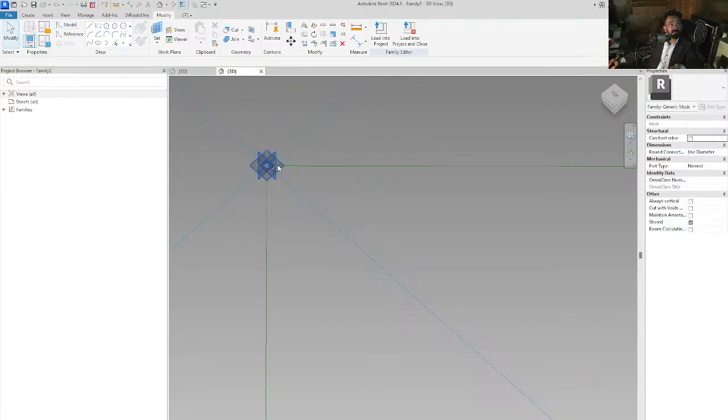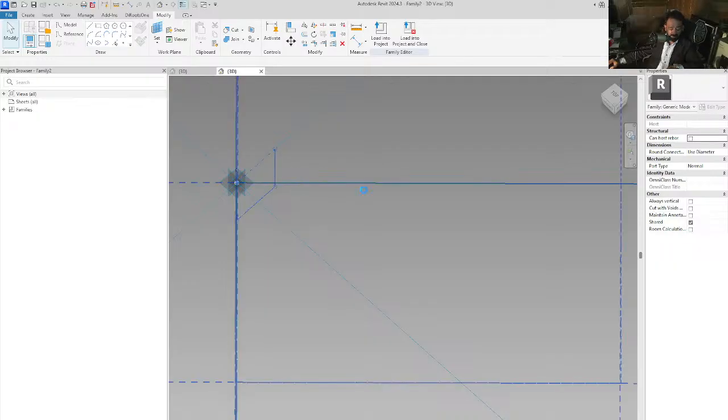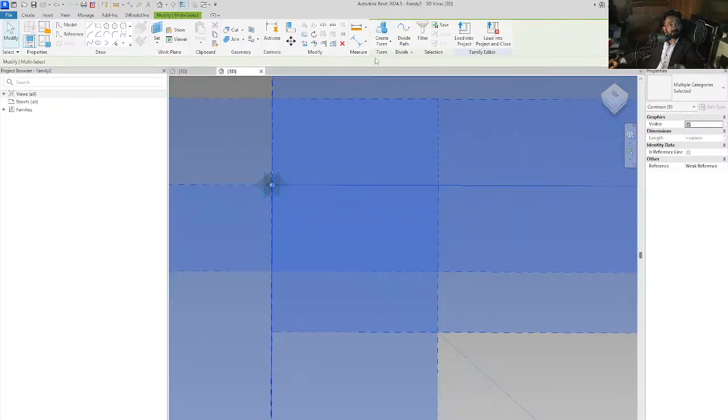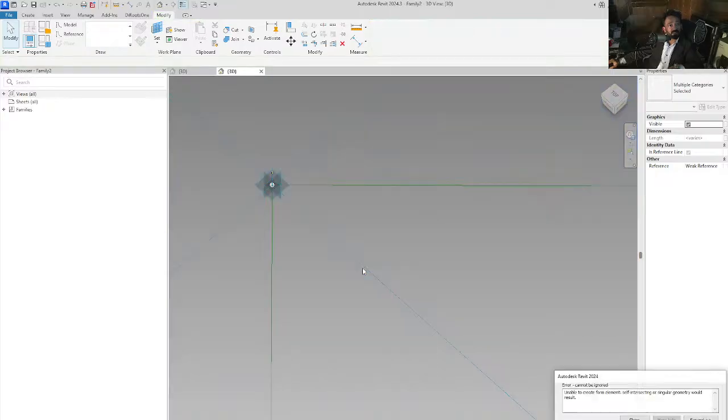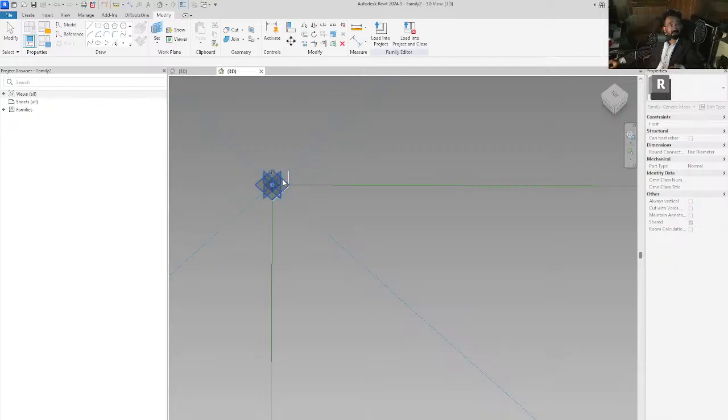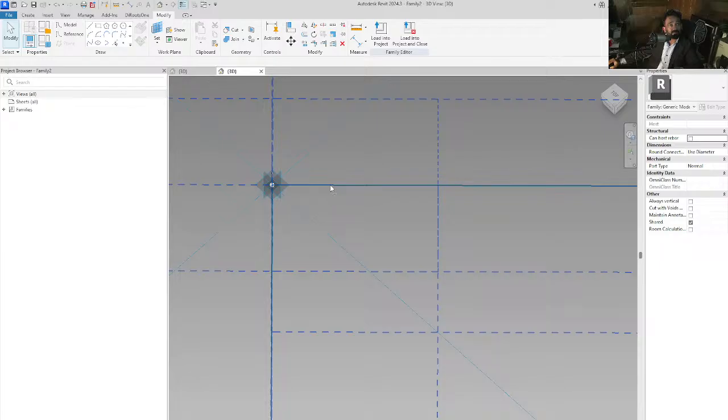Now if I select the shape, which is this, and I select the whole frame by pressing Ctrl, then I am going to extrude these and see how I can make something like this. But here, because of the reference plane, this is not possible. So I delete this side, and then I will go for my frame.